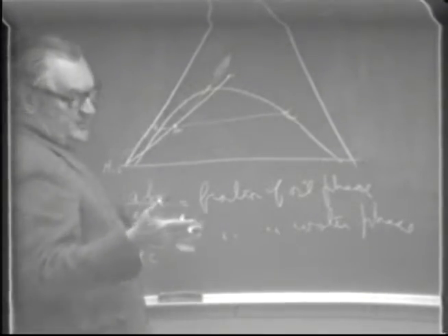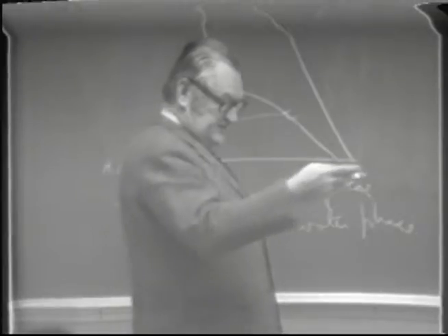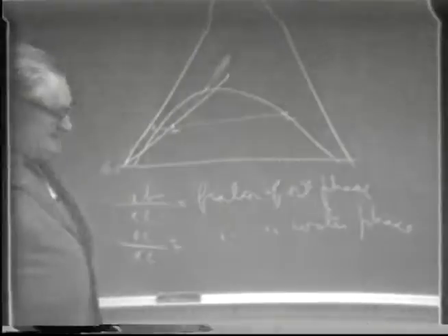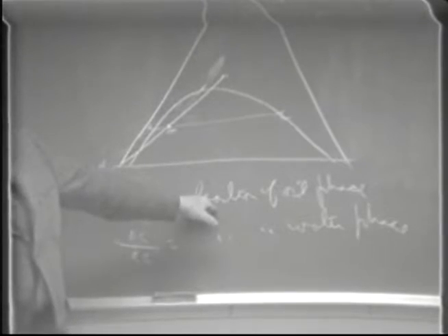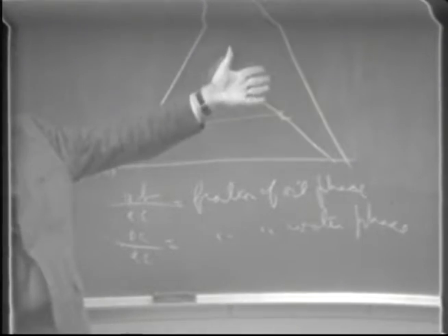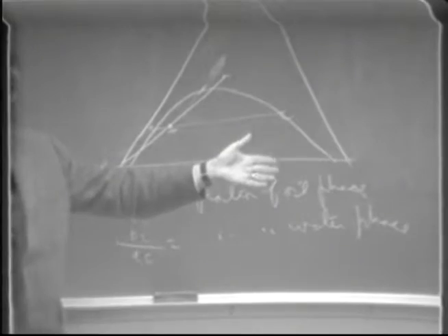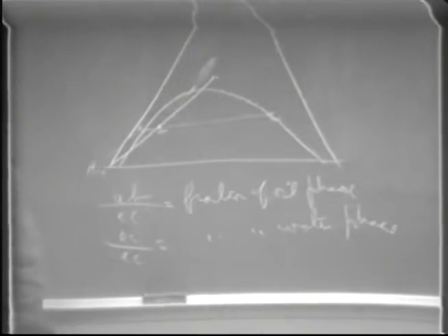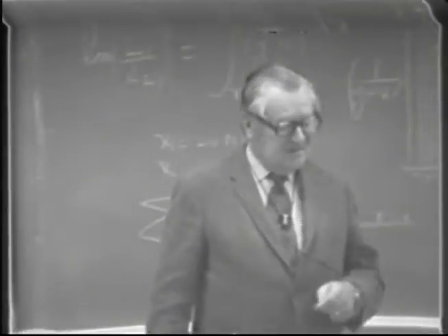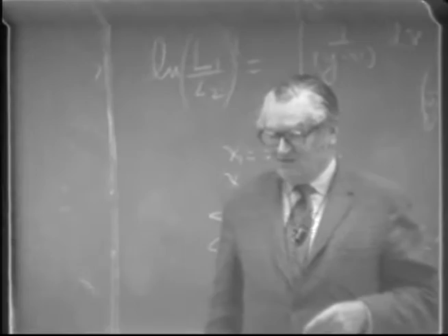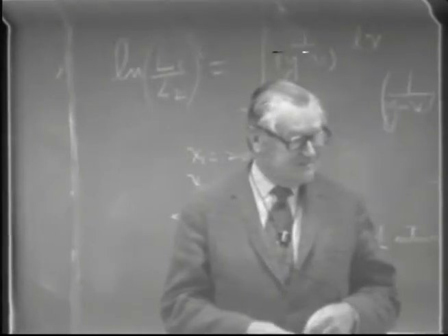Well, from the stated requirements and the solution here to part 1, you can get the grams of the oil phase produced. Because let's say you're going to take 100 grams of the original mixture as a basis. That'd be the recommended basis, or 100 pounds. And you add, what is it, 2 parts of water? So in other words, you added 200 grams of water. So you got a total of 300 grams in your dilute mixture.